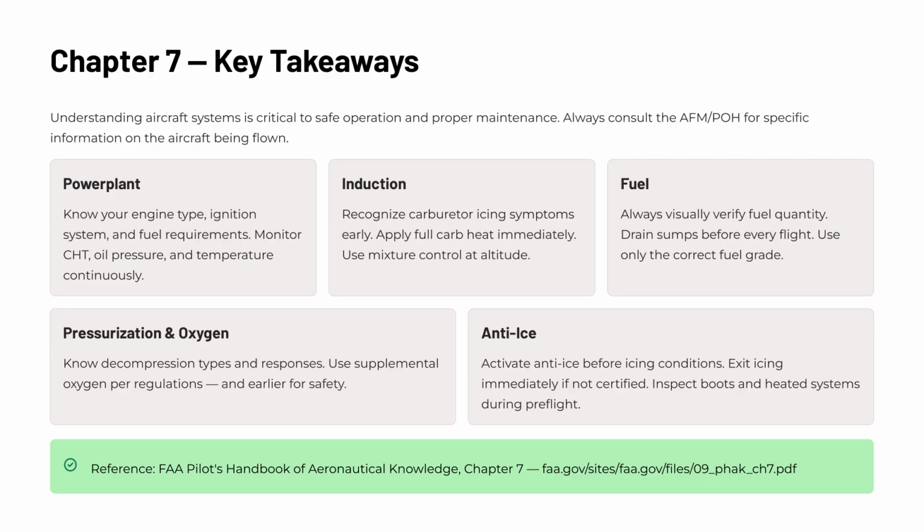Finally, with anti-ice systems, the key word is proactive. Activate systems before entering icing conditions, not after. If the aircraft isn't certified for flight in icing, exit those conditions immediately. These takeaways, applied consistently, form the foundation of professional airmanship.